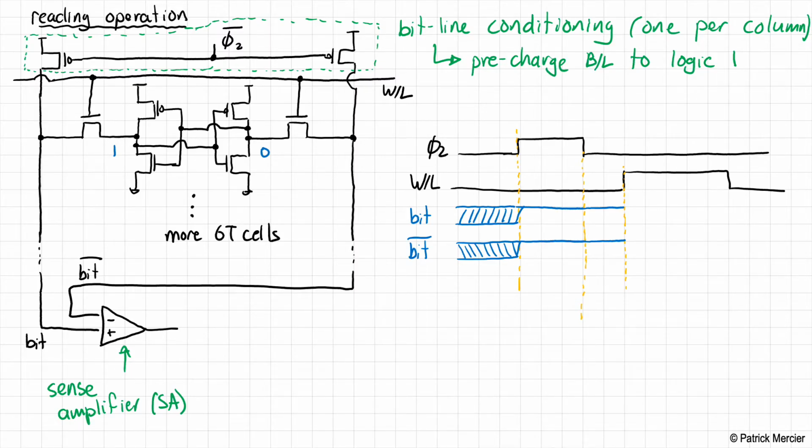right? On the right-hand side, we have a logic 1, which is the same as the pre-charge value of the bit line. So nothing is going to change for the bit line. But on the bit line bar, we have a logic 0 being stored. Meanwhile, we had pre-charged the bit line bar to logic 1. So there's a conflict here, right? And it turns out that the SRAM cell is going to win.